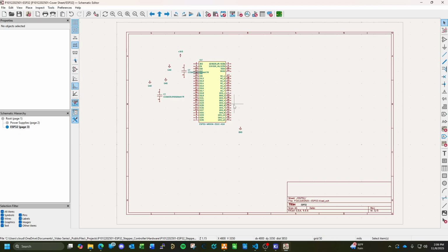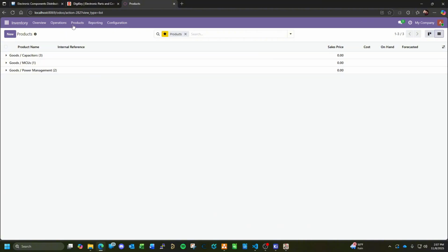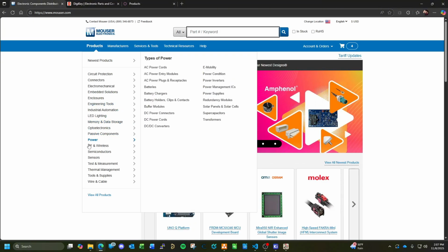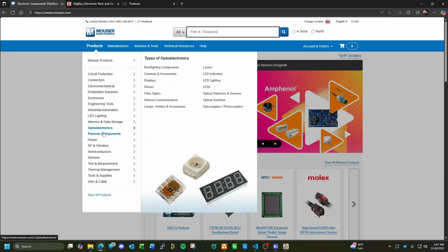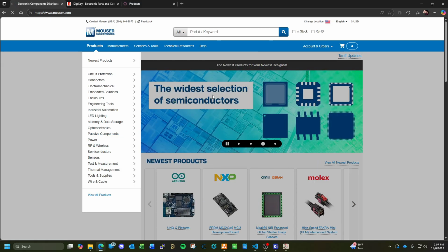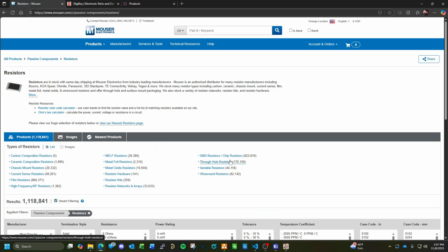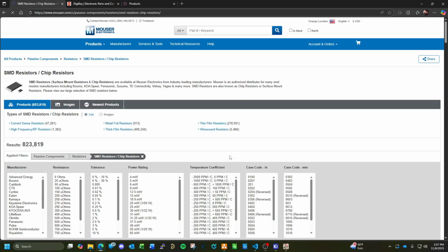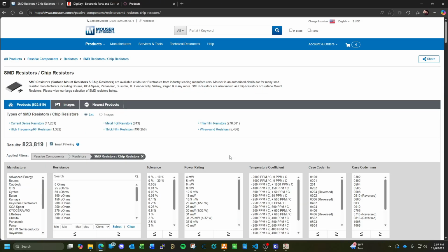So I'm going to use a 6.8 k ohm resistor, very similar to how I set up the master clear pin, which pretty much does the same thing. It holds the device in reset until the power supply is stable. It's basically an RC timer network.